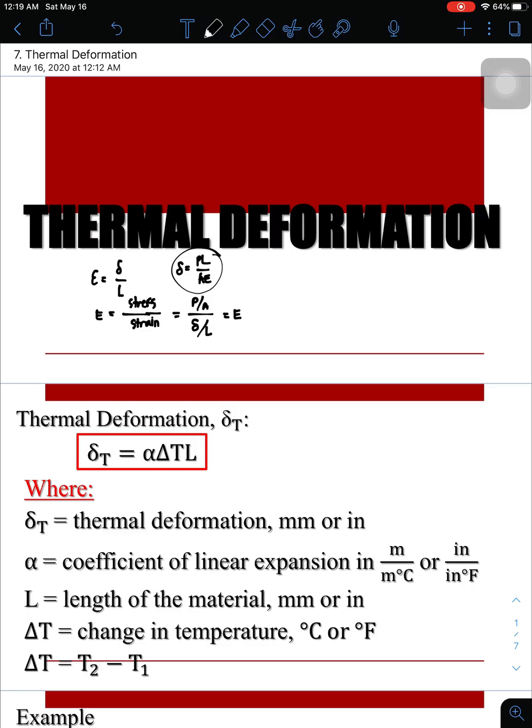Whenever we consider a drop and rise of temperature, there would be an action on internal forces inside the fiber, and because of the dropping or the increasing of temperature, we collectively get the force inside as the axial force, and we could relate it to the axial deformation.